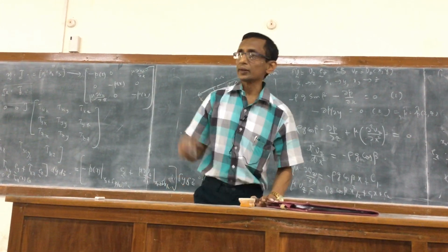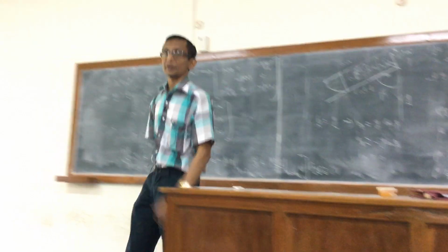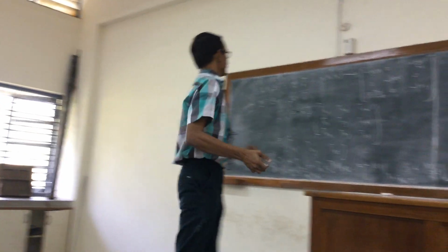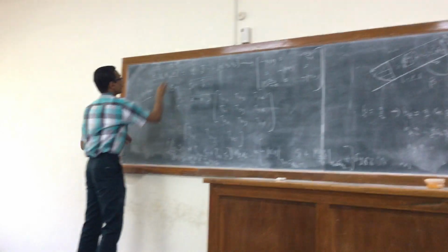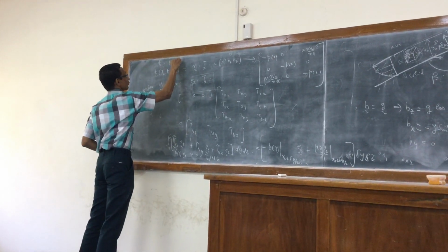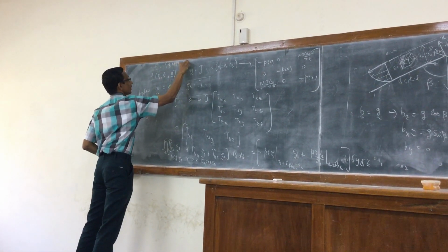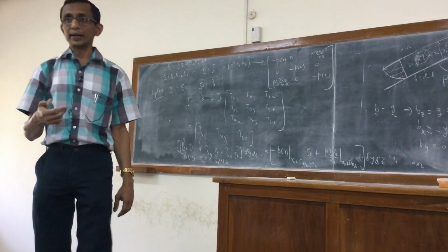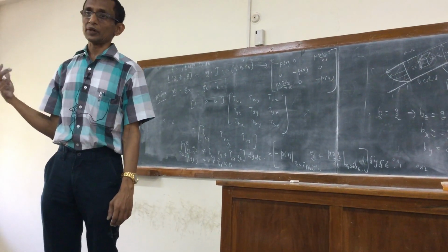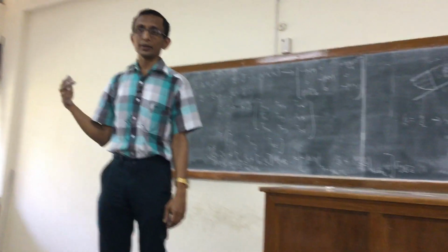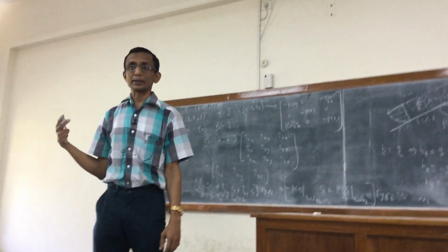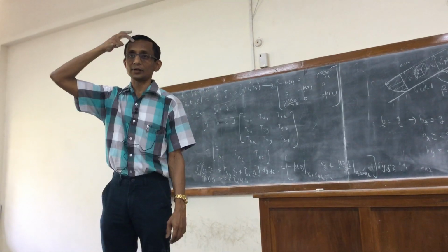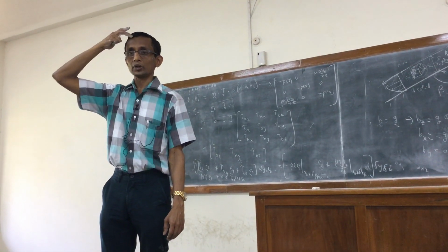No, contact force. See, the normal for each of the phases is different. So we have to do the contact force because of the integral of t = σ·n dA. The reason we are doing it for the 6 phases separately is that the n for each of the phases is different. So I have to calculate the contact force separately for each, and then we can do it as the divergence of the stress tensor over the volume.